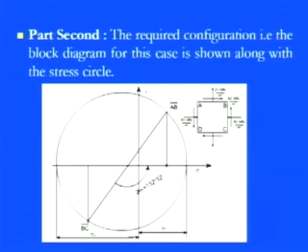So the part 2, in which the sigma x was the compressive one. You see the problem here in this slide, this is my square element, this sigma x is the compressive one, sigma y is the tensile one, that is 25, this is 85, and this is 60 in the clockwise direction. So now, keeping these things, put those values of sigma x, sigma y and get these. This is my main center coordinate through which it is passing.